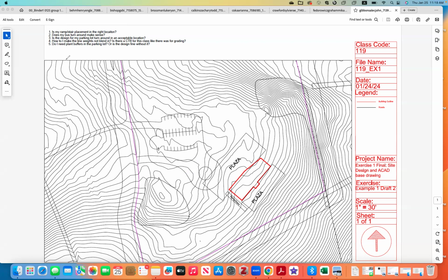For now, you would start thinking about where you should have plants or vegetation in the parking lot, right? It is either at the outside, along the edge of the parking lot, if you're directing water away from the building and parking lot, your vegetated area will be in these locations, which means in this area, you should not get too steep.